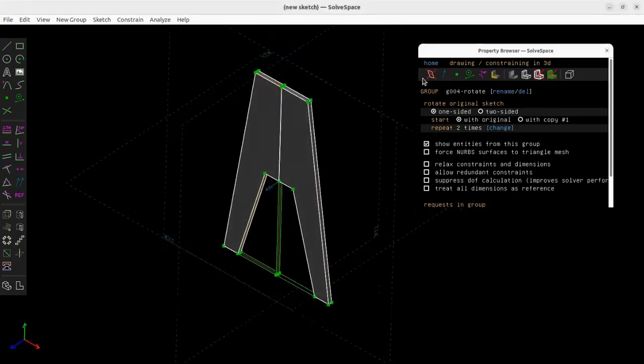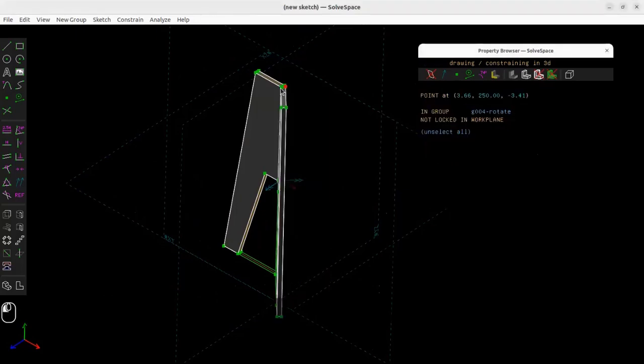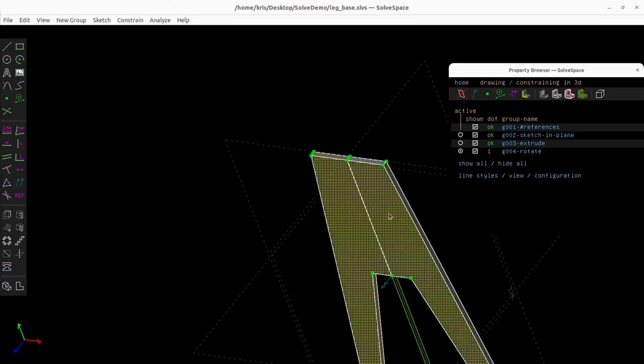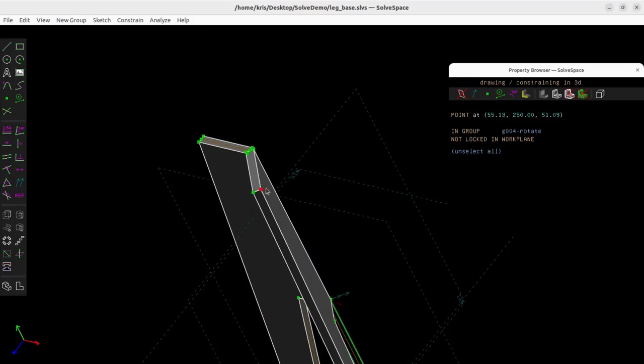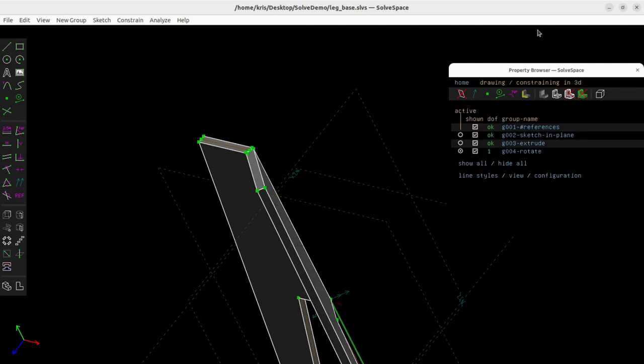It's like a solid object, and we can go back here to the main view home. I think it's also floating a little bit in the air. Yeah, the rotation is not really constrained. One problem you see here is that when you grab one of those points and move it around, it's going to rotate in an unpredictable manner. And over here you can see that we still have 1 degree of freedom left. We want to bring it down to 0.